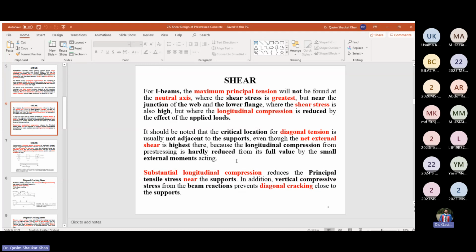And if you recall, in Mohr circle, we said that the principal planes and the shear planes are 90 degrees apart. And on the element, principal planes and the shear planes are 45 degrees apart. And we generally say that the shear is maximum at 45 degrees with reference to the longitudinal axis. So everyone remembers this point, that the principal planes and shear planes are 45 degrees to one another on the element, and the shear is maximum at 45 degrees.